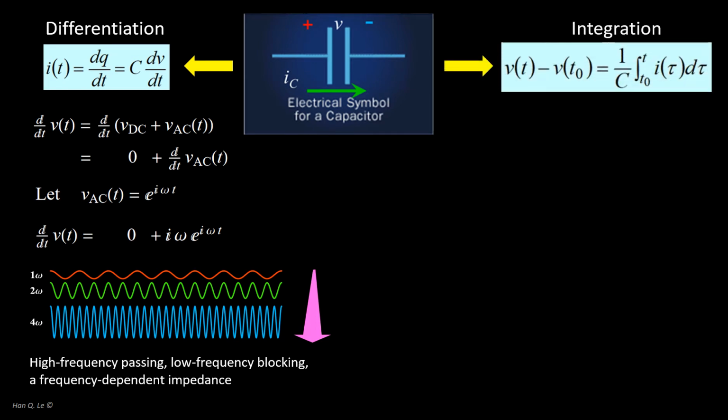Consider input current I to a capacitor. The voltage is an integration. Let input current I be the sum of a DC component and AC component. Then the DC term cumulates versus time. This is the accumulation of charge on the capacitor that we have seen previously.